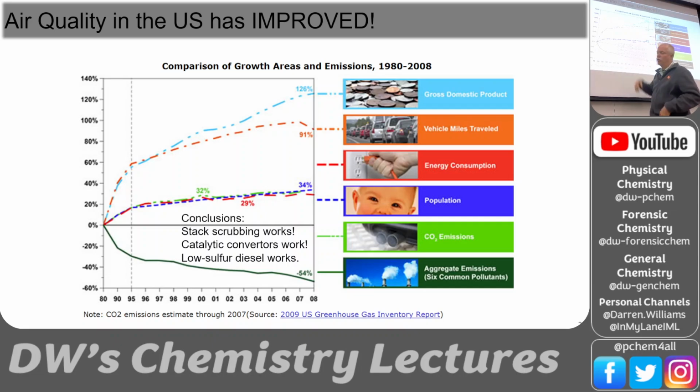And then stack scrubbing. So in our coal-fired power plants, the somewhat polluting and somewhat reactive gases come out, and they are sprayed with water. So they spray the water in, and all of those lead oxides and mercury oxides and all of those contaminants get entrained in that water and fall out to the bottom, calcium oxides too. And then steam comes out the top. So we're dropping out all of the water soluble oxides, and we have the ash from that burning that collects in this pool.